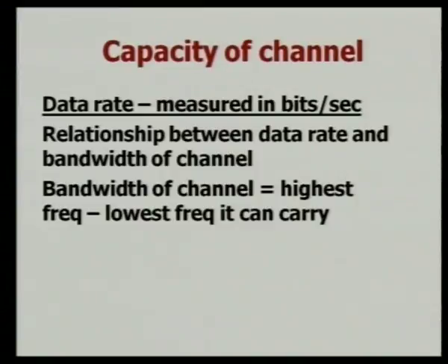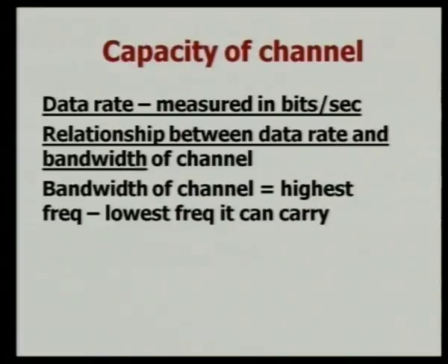Next thing we need to look at is what we mean by the capacity of a channel. Given that you have a certain amount of attenuation that can take place, and a certain amount of noise that is inherently present in a system, how do you determine how much data can be carried by my communication channel? Here there are a number of people who worked on some very interesting results. So we will take a look at one or two of these. We want to calculate the data rate, which is typically measured in bits per second, given that you have a certain bandwidth for a channel and that there is some amount of noise. So we need to find out the relationship between the data rate and the bandwidth of the channel.